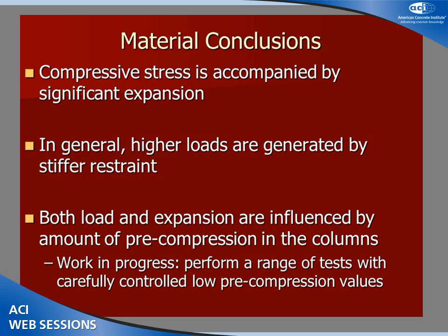The columns were capped with the test heads and tightened in order to maintain contact with the load cell. This necessarily induces a pre-compression on the columns, and the amount of pre-compression that results obviously has an impact on the material behavior moving forward. As a work in progress, further research will be to perform a range of tests with carefully controlled low values of pre-compression to determine sensitivity.